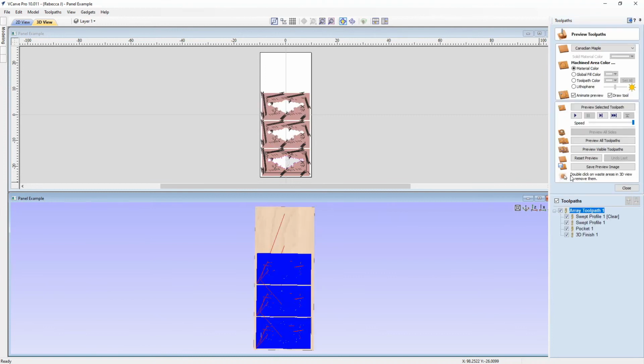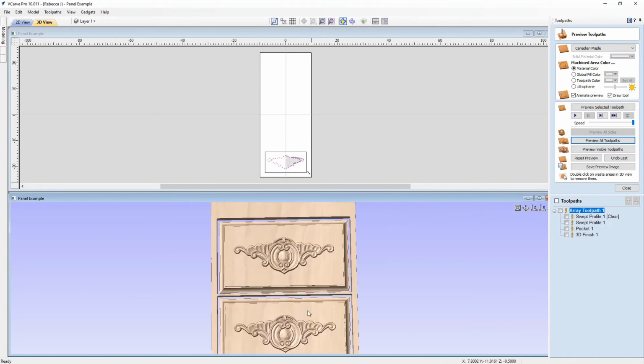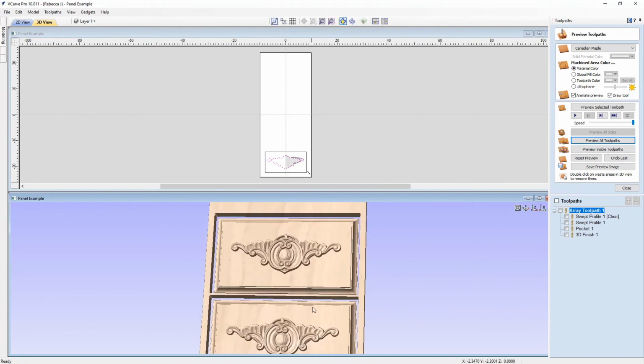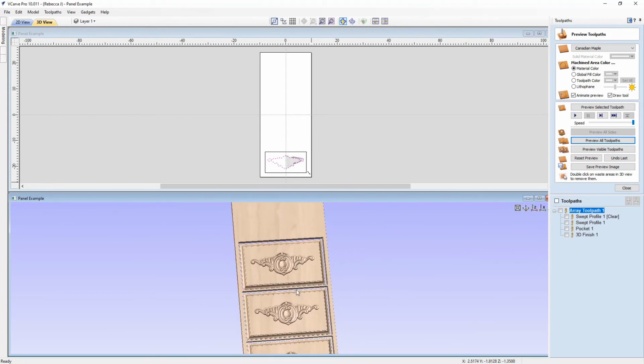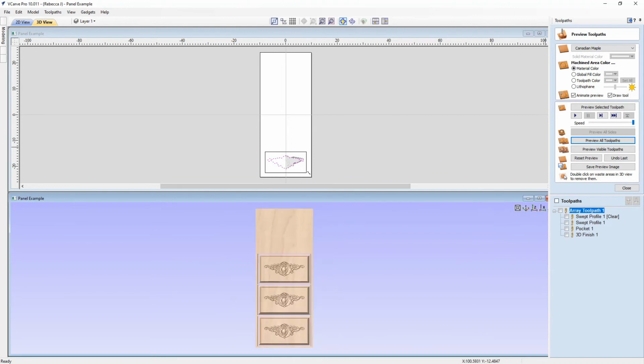You see that the software will do that for me, and obviously we can create more copies if we wanted, and then we could go ahead now and preview all of the toolpaths, and we can see how the part looks there. And so this is another way of combating multi-machining when you're working with single STL data. Okay, so that's that example there.